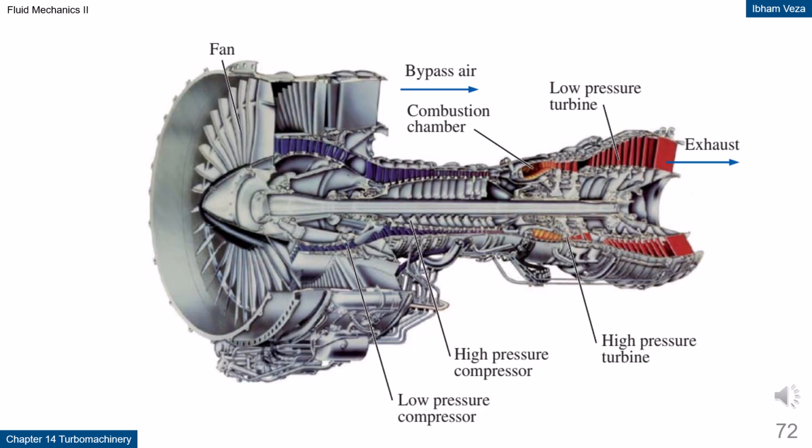Multi-stage axial flow turbomachine. This figure illustrates the staged arrangement of rotors and stators working sequentially along the flow direction. Each blade row adds or redirects the fluid momentum before it enters the next stage. The visualization clarifies that the total pressure rise does not come from a single impeller, but from the accumulation of many stages. The flow remains predominantly axial, making it suitable for large flow rates with gradually increasing head. The figure emphasizes the importance of stage integration within one machine.